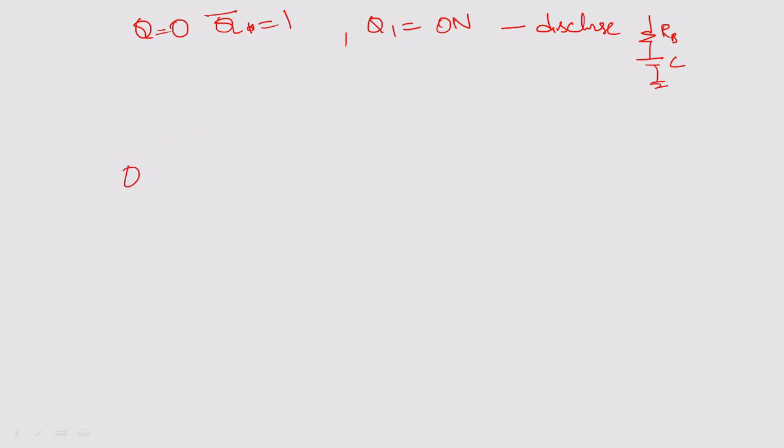Right? Now consider your capacitor voltage is 1 by 3 VCC, very close. Okay, so the capacitor voltage is less than 1 by 3rd of your VCC. This is a voltage which is connected to the plus terminal of your comparator. Consider it like this, plus, minus: it is connected to plus and minus is connected to this. Okay, that means what is the comparator output? Comparator output will be 1. So that means S is 1.